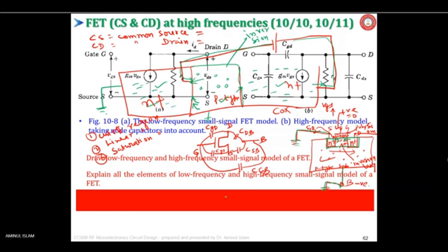With no bias, you have a simple PN junction, one side N type, one side P type. Actually, it is N plus type and this is P minus type. P minus indicates lightly doped. N plus indicates heavily doped with pentavalent atoms, phosphorus for example. This is boron, as you said.